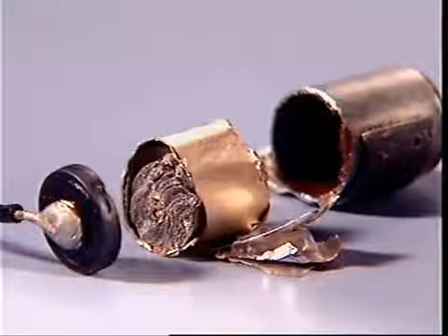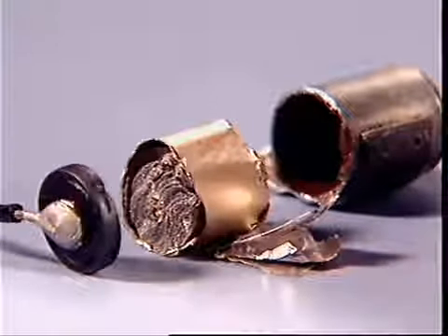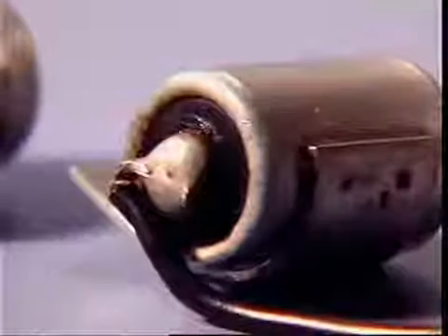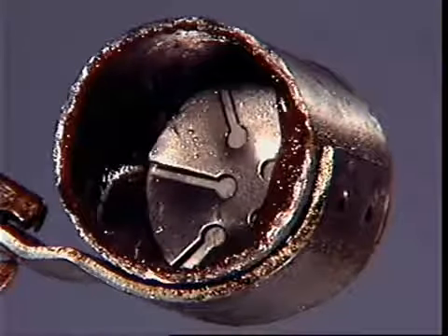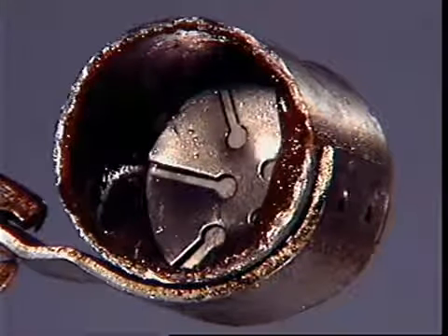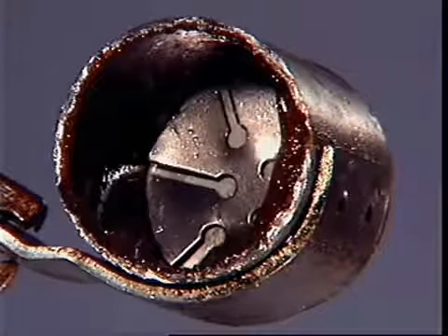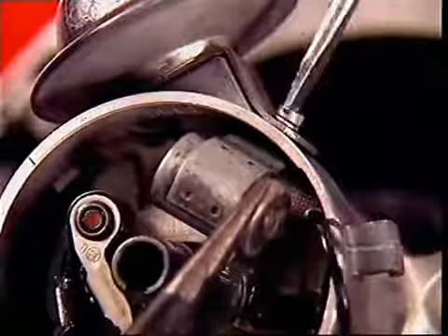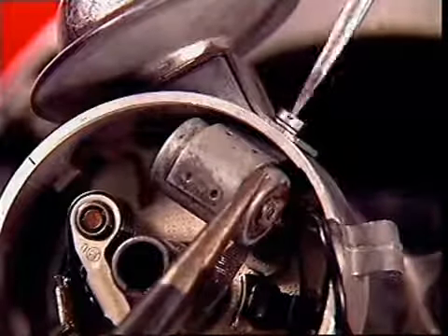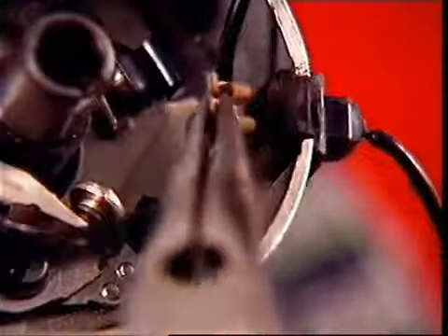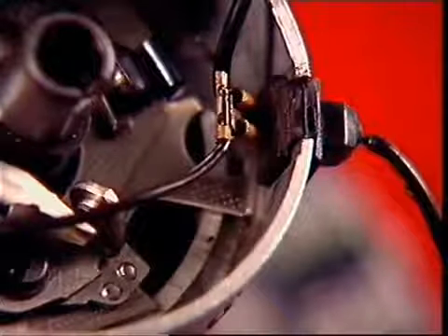The plates and insulating paper are rolled up tightly together and sealed in a metal can by crimping the end over onto a gasket. A spring in the base forces the plates and insulation against the gasket to keep out moisture. One plate is connected to the capacitor case and through its retaining screw to ground. The other plate is connected to the external connecting lead.